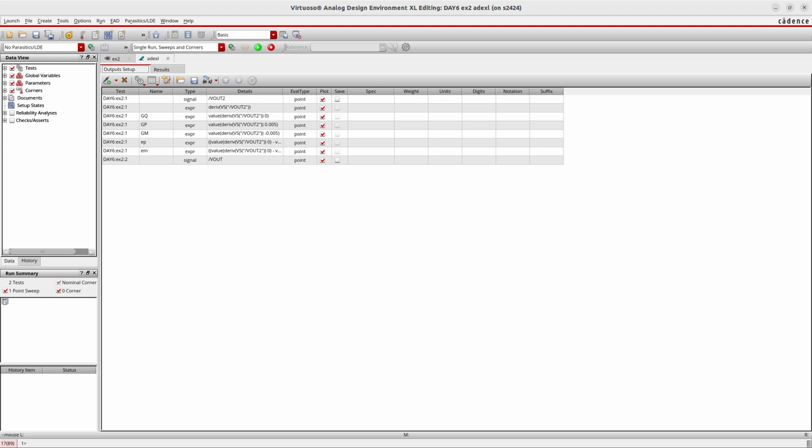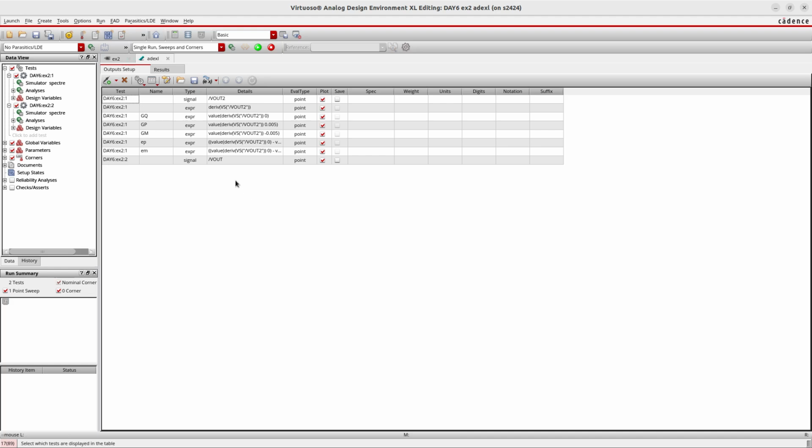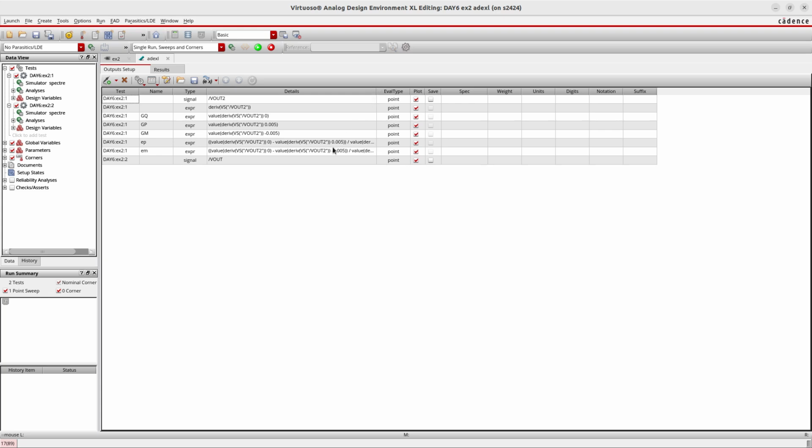There is a template that is going to run both a DC sweep and a transient simulation to compare the results of nonlinearity taken from the differential gain, or nonlinearity taken from transient simulation and spectrum analysis. Doing it will require setting a number of equations to extract the errors, and then extract the distortion of second order and third order.